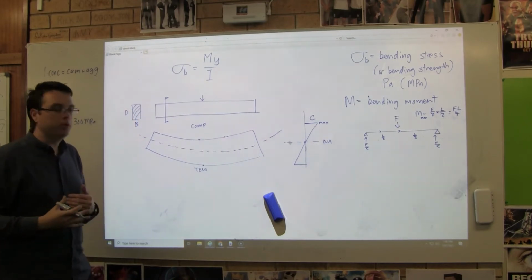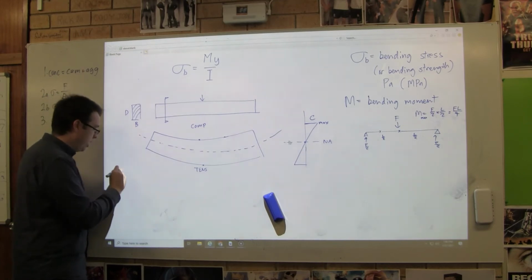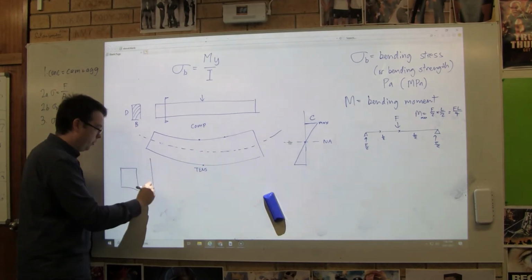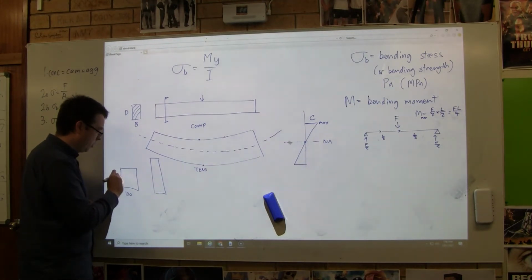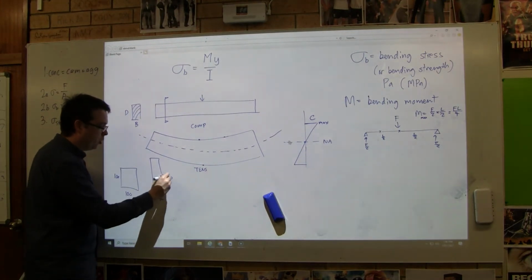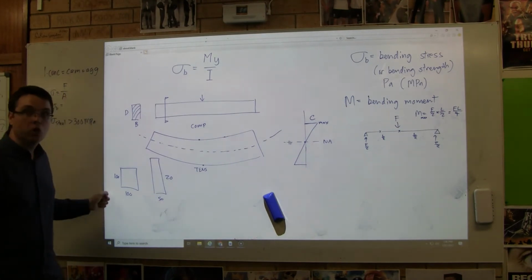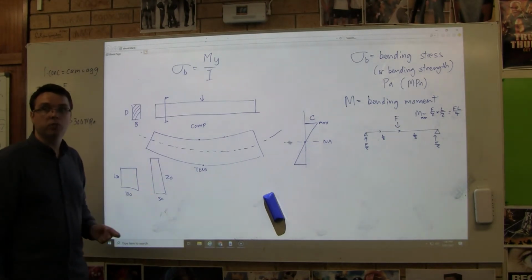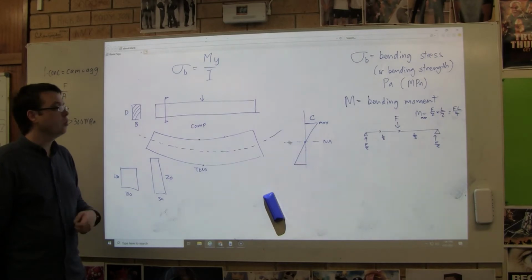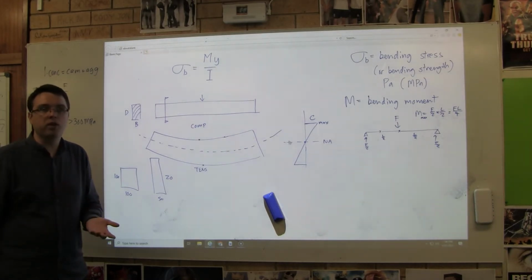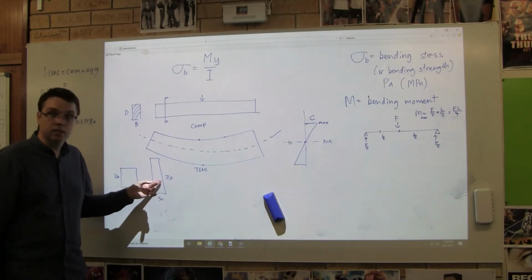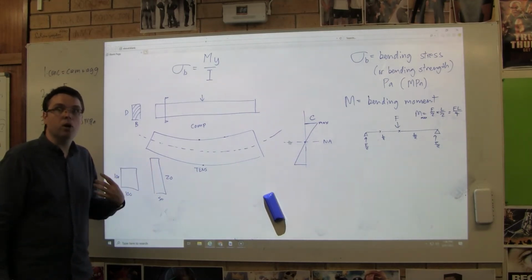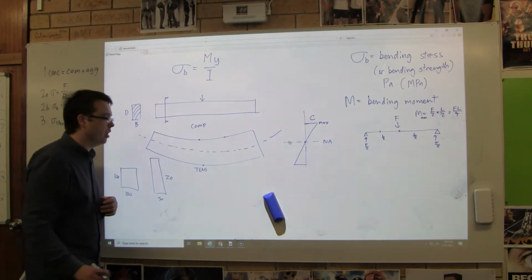And the bigger the depth, we've talked before about how if we have two beams, I could buy a beam that's 100 by 100, or I could buy a beam that's 50 by 200. Well, this one's much better for columns, and this one's much better for beams. And this is why roof beams, which we call rafters, or floor beams, which we call bearers or joists, tend to be taller rather than equal sizes.